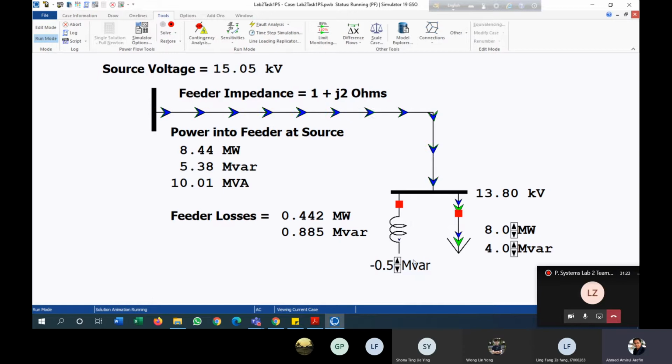Okay, so this is basically the voltage regulation formula for your network. One more thing you can do for the initial stage, where the source voltage was 14.98 and the receiving end is 13.8, you can calculate the voltage regulation, and then once you are changing, like you can change for 0.5, 1, or maybe 2. Okay, then make a small table and calculate the voltage regulation.